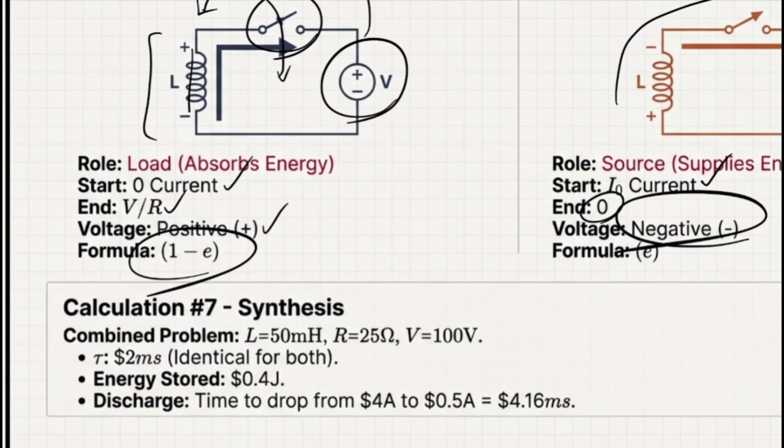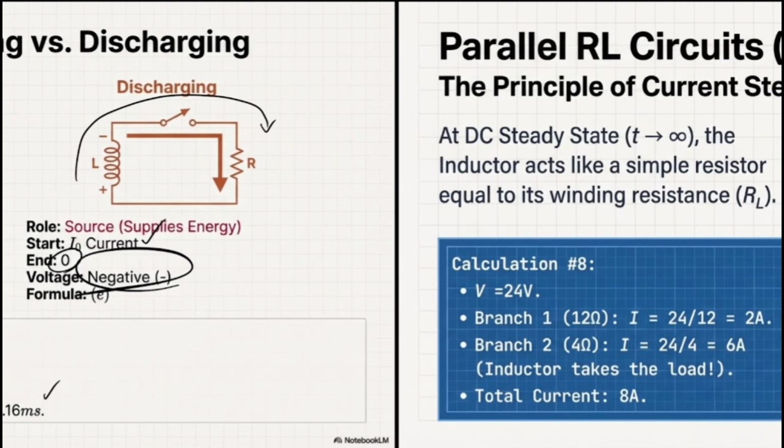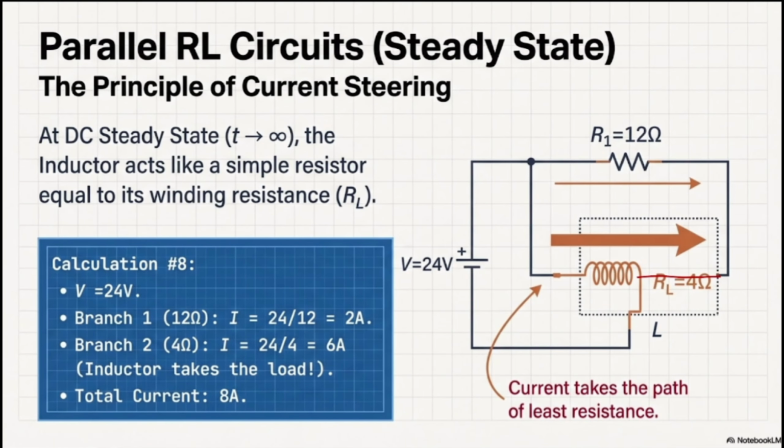We have a very small calculation over here. Obviously you can pause the video and find those solutions. It's not that hard. Then let's compare your answer with these. So what would happen if you have a parallel RL circuit? Because so far we talked about the series RL circuit. As I just mentioned, nothing would change that much. But the important thing you have to be careful about is your time constant, because it's not going to be simple L over R anymore.